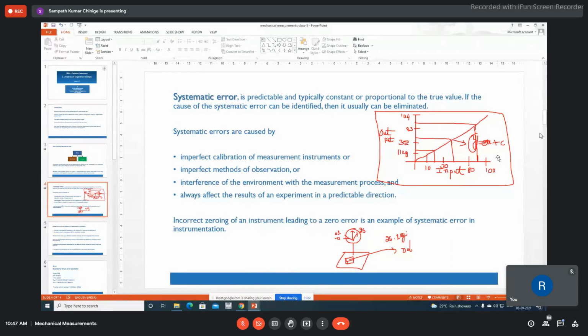But what happens is, the principle is you have a fine thin wire to which you keep giving current, all right, and when flow takes place over it, it cools down the wire. Therefore when the temperature is reduced, your resistance will vary. Therefore for a given current, you have a different output.